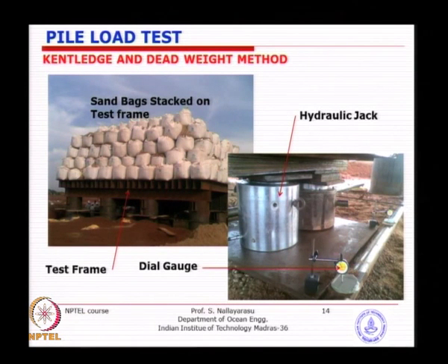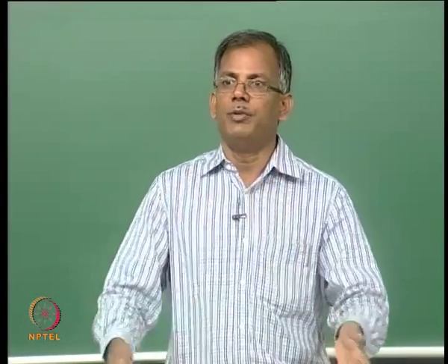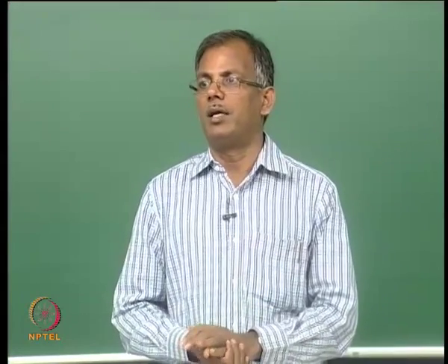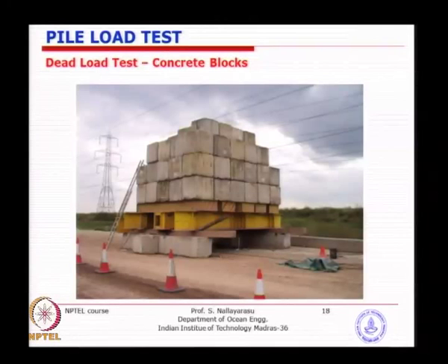Only the stability of them is sometimes a bit of a worry, because even a smaller eccentricity caused by either placement or by stability, the whole thing can be turned. In many places if you notice, pile load tests failed because the Kentledge tilted or the Kentledge failed, which will cause quite a bit of problem. Whereas using concrete blocks is quite useful because it is very stable.